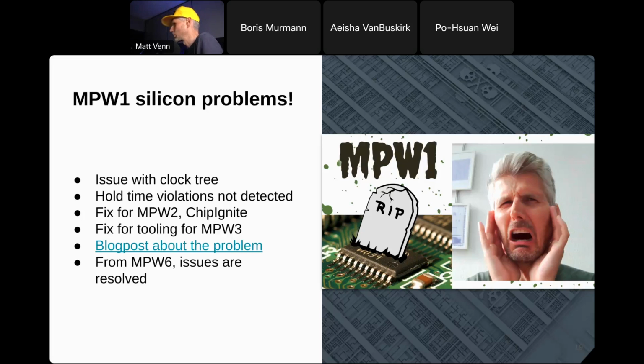Kostas says, what is the cost of packaging and testing? Actually, it's rare to get bare dies. You're much more likely to get QFNs, which are easier to solder and handle. And at least with the eFabless service, they also solder them onto a little breakout board so that you can get started. With Tiny Tapeout, we also solder them onto a breakout board.